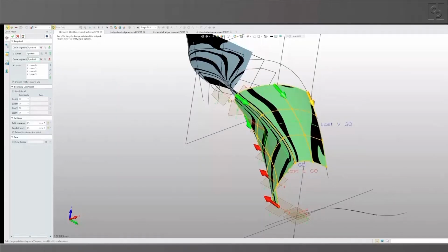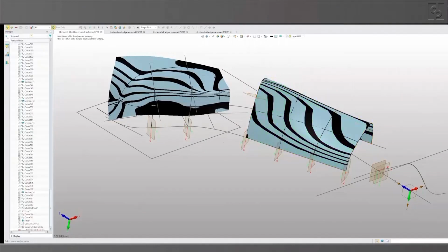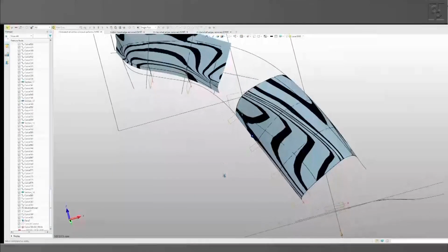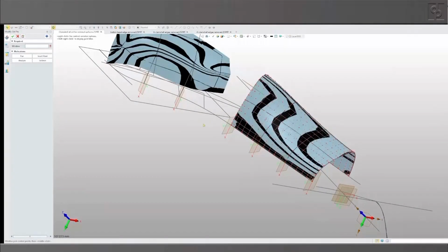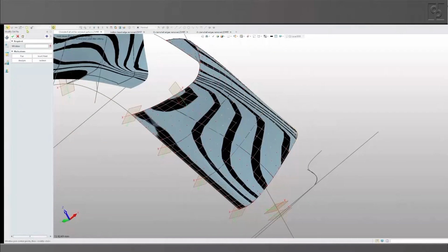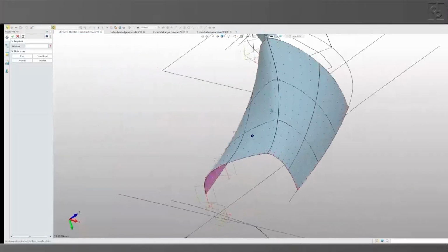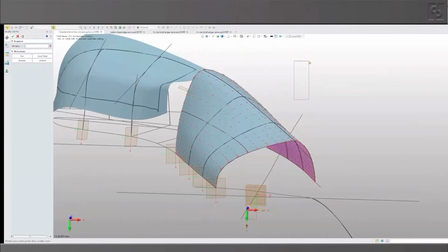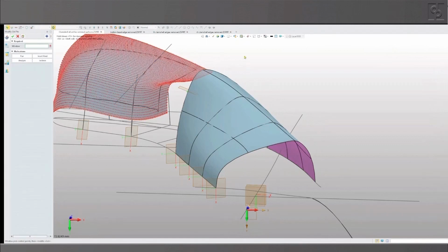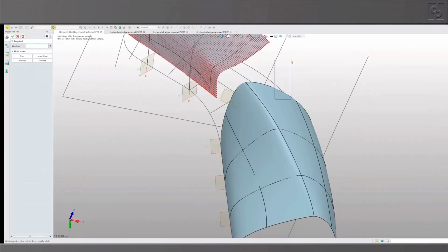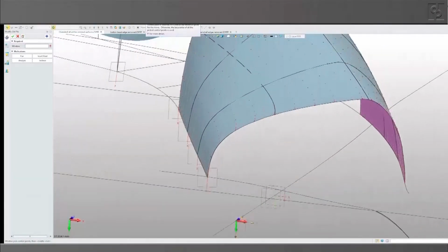What you see, or will see, is that the number of control points on the manually generated surface is far fewer than the number on the automatically wrapped patch, and it's certainly advantageous to have the surfaces as simple as possible to give the amount of curvature that you need. When you have as many points as are on the automatically wrapped patch, it means that it's probably rippled and probably not the shape that you actually want it to be. I've overlaid this on the scan, and I can tell you there isn't really much to complain about.